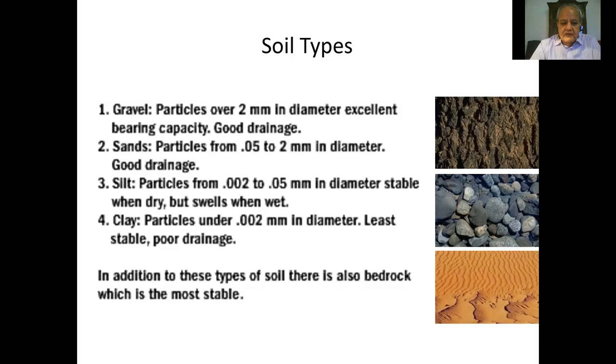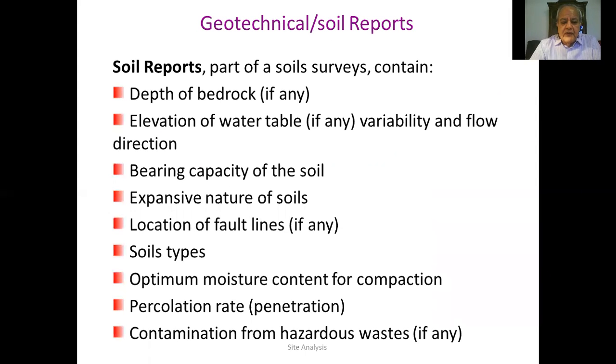Sand is the most appropriate in terms of bearing capacity and drainage. Silt is very problematic because it swells when it gets wet. And that creates instability in the structure afterward. Clay is also problematic because it has poor drainage capacity. So it does not let the water go through it easily.